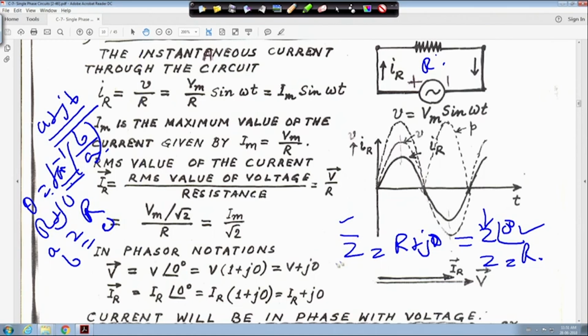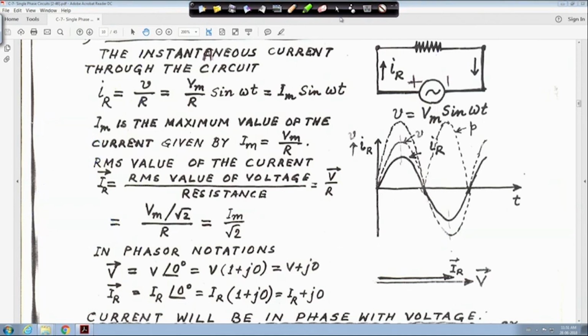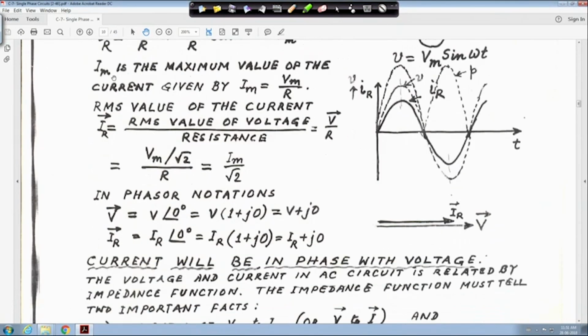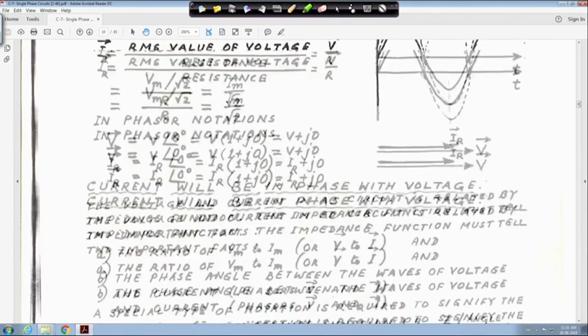We do not represent this with an arrow. When we go through it, I will try to rectify the writing errors, two or three places. Do not put an arrow, that is not a phasor quantity. To represent a complex number you put a Z bar, it is not a phasor quantity. Voltage and current both are phasor quantities, but impedance is not a phasor quantity. This is the notation.